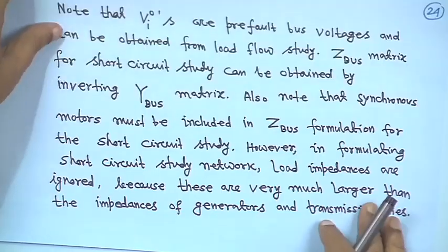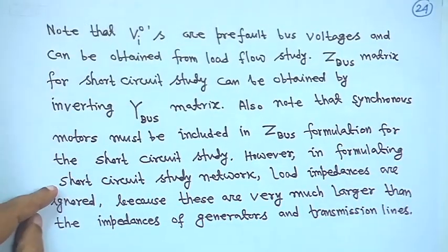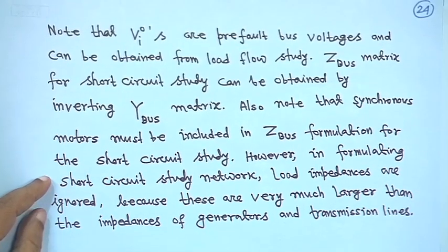So, you excite that by the pre-fault voltage, minus VR0, in series with your fault impedance, and accordingly all other calculations are the same. That means in the equivalent network, the current injection at the faulted bus will be minus IF, and for the rest of the buses there is no current; all current injections are 0. Based on that we got this one, right.